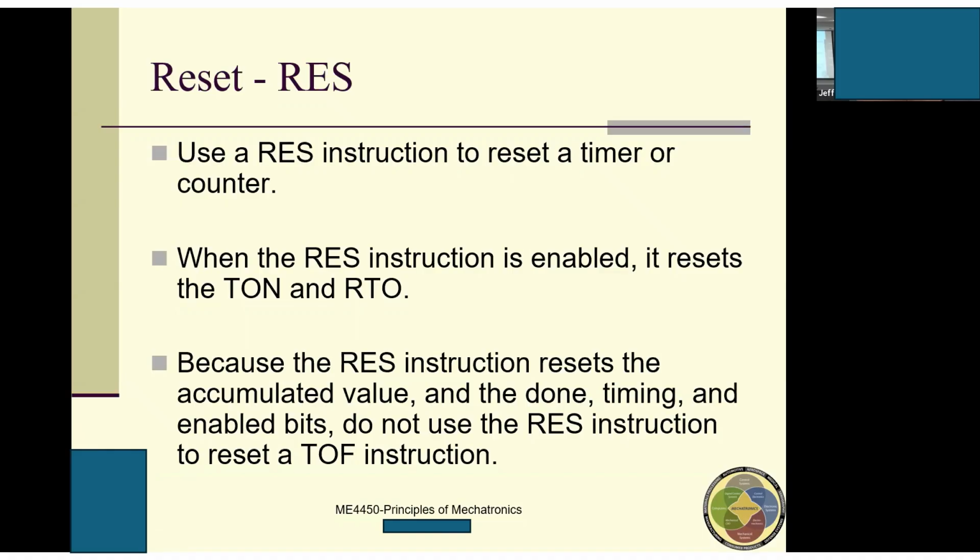So I told you guys, this is a very good idea: to memorize two things, compare these two things and know the differences between them. Knowing the difference between these two similar things can reinforce your understanding. Why can I not use RES to reset the TOF? The reason is that TOF is triggered by a true to false transition. If we use RES, you just trigger it. If you trigger it, this timer starts counting. You understand?